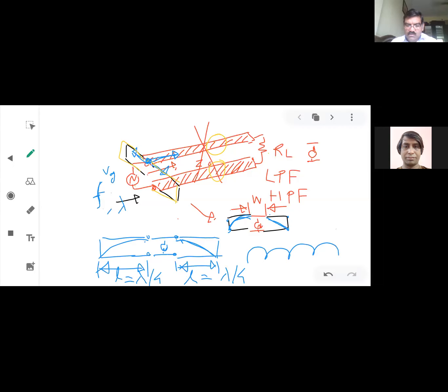Whereas the other two currents are not moving in the direction of the load, so these can be termed as reactive power. Now, after that, it was shown that if your transmission line is operated at smaller and smaller frequency, then the standing wave gets shifted. The minimum of the standing wave is going to remain at the same location, that is, at the shorted end.